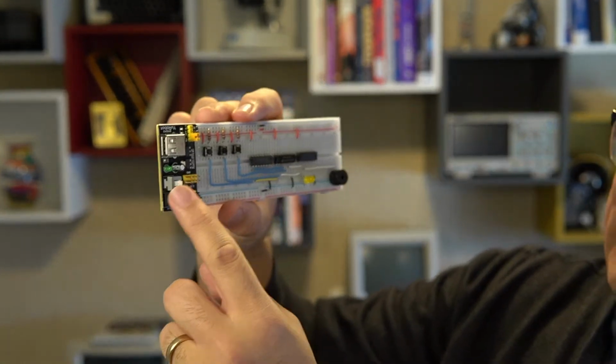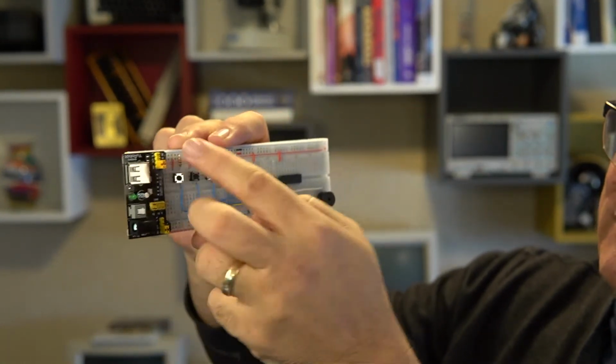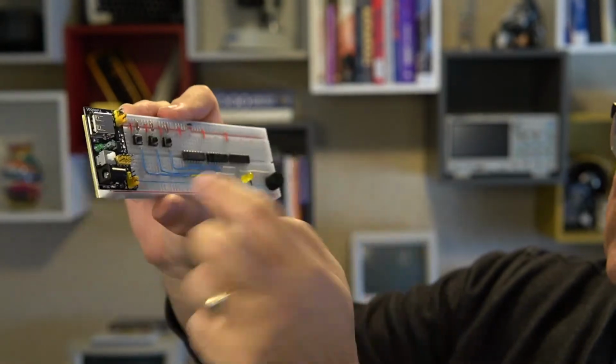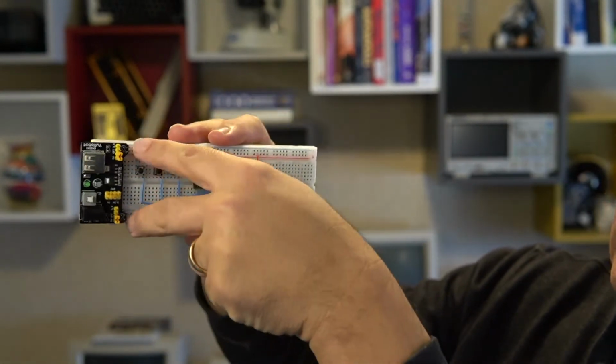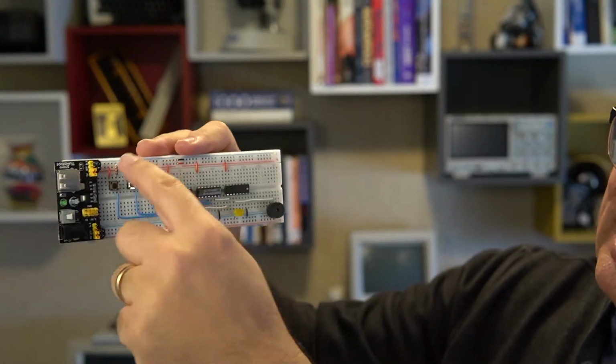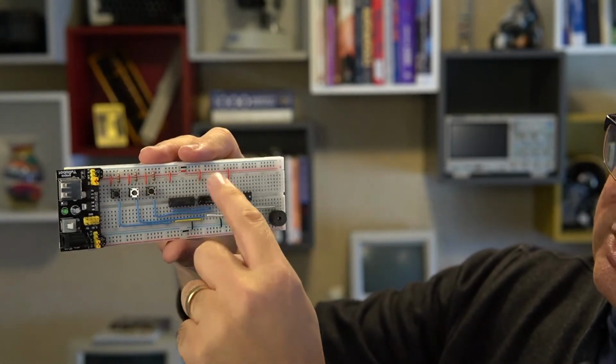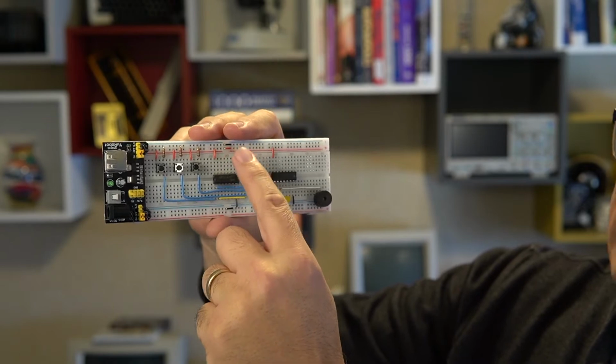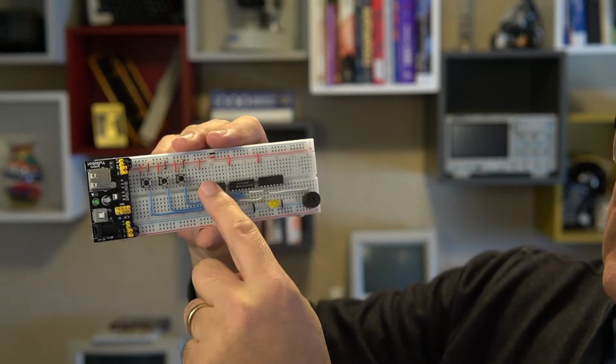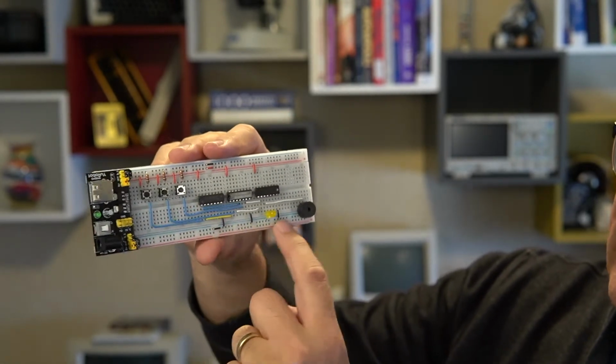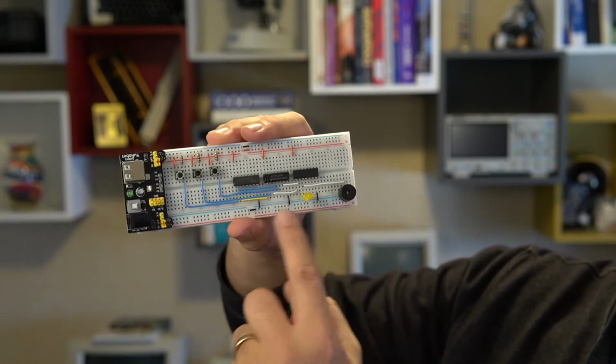So this is a power supply, just so I can hook up a battery to it, and then it feeds power into this. This is called a breadboard, by the way. And it feeds power into these rails up at the top. And then these little red wires here are showing the 5 volts being pulled off these rails and fed into these chips. And then the black wires down here are connected up to what's called ground.